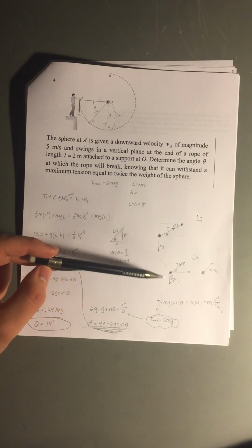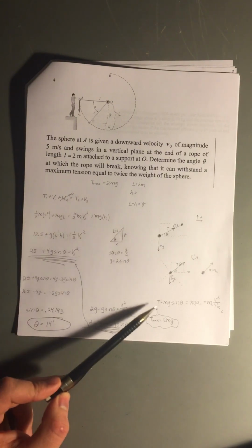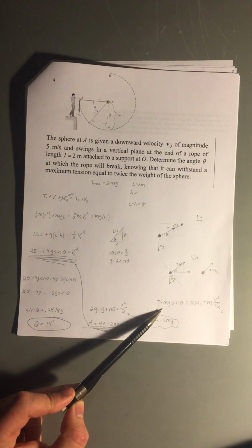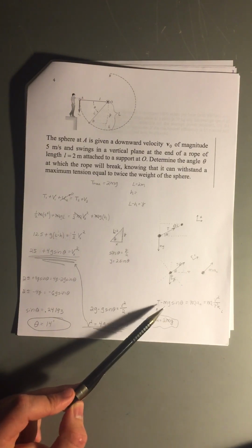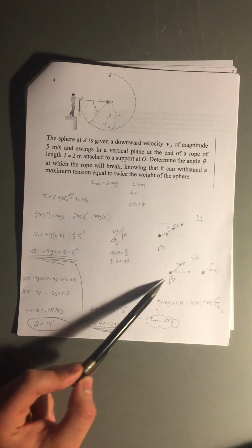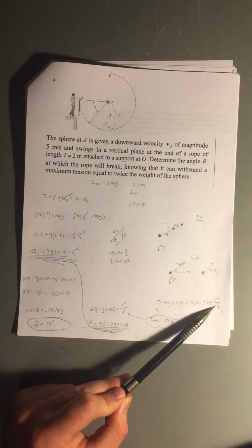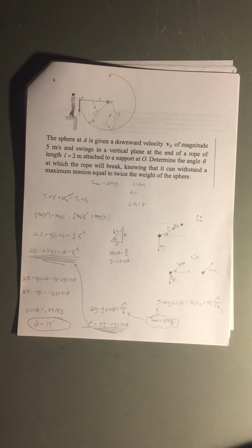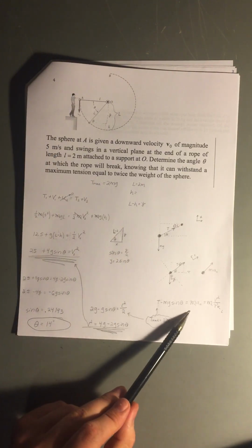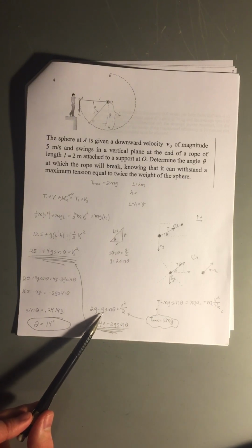And so what we do at this point is just take this diagram and create an equation from it. So here are our forces that equal mass times acceleration. So we have tension minus the component of mg in that same direction. And then we can replace our acceleration with v squared over rho. And in this case, our radius rho is just the length of our cord L. And so rearranging this equation and solving it for v squared is what I've done here.